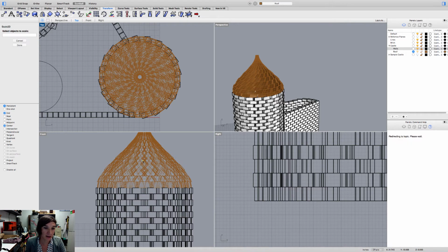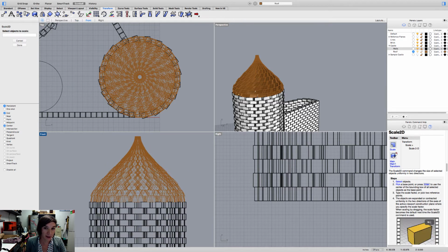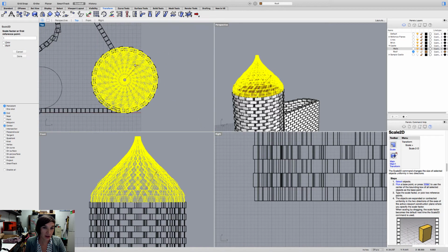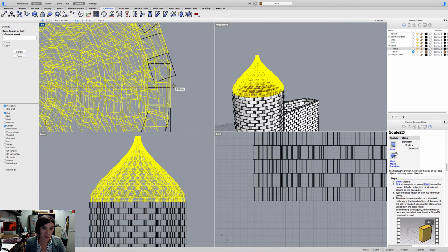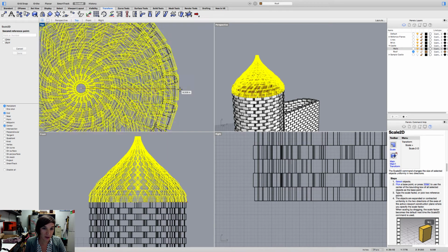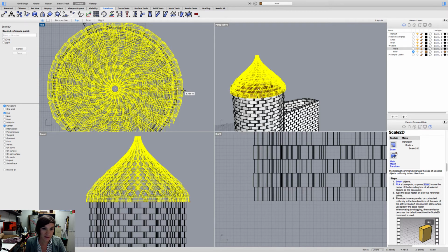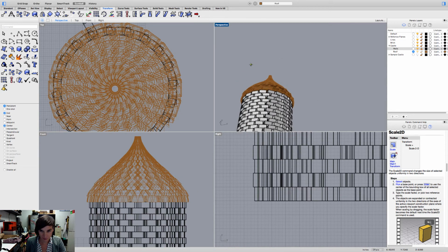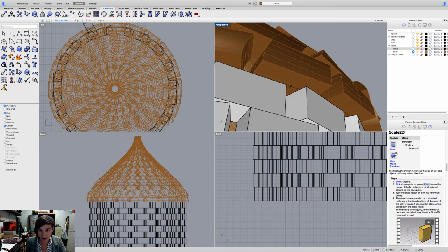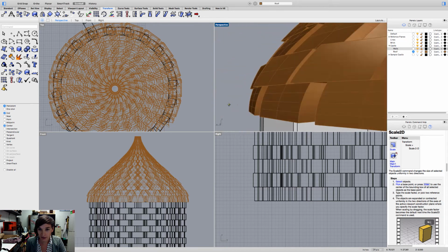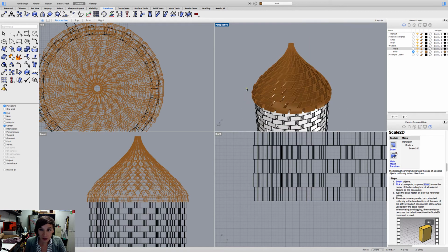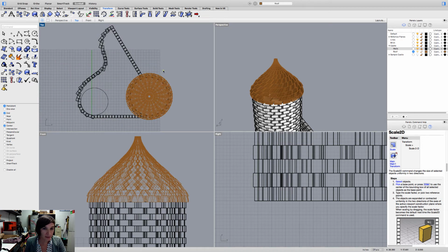Let's keep it at the same height, going up, and we just want to expand it out so it looks like it's going over the edge of the wall. So we're going to select our group here. Again, we're going to select the center of the circle. We're going to come out and we're going to say roughly about there. If we wanted to, we could get exact, and we're going to scale it out a little bit. Not a whole lot. And then that scaled everything outwards. And if we look up at the edge, we can see that it is right there. So that's super nice. You can also put in fine numbers for that, but right now we're just getting familiar with working in Rhino and the different orientations and things like that.